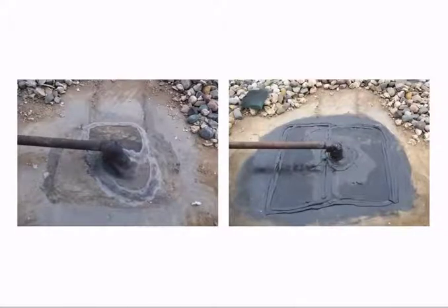Here we have your typical gas line, low to the roof surface. Maybe during the original build that gas line should have been raised up, with a pitch pocket with some pourable sealer installed into that, and a nice metal cap over that to prolong the life of that sealant. But they did field wrap that, and they wrapped their membrane up onto the existing patch, up onto that pipe a little bit. With the movement of the pipe, it's going to crack that membrane.